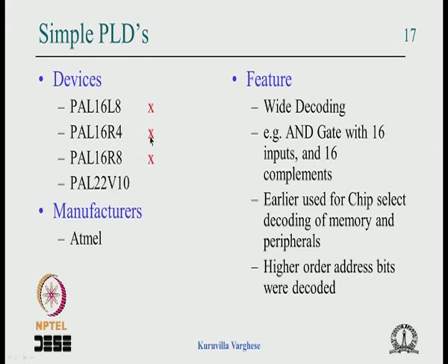It's of academic interest to understand, maybe the only device which is being used nowadays is among the complex PLDs. So the PAL22V10 is a much more flexible version, which combines all these together. We will see that architecture, and Atmel still manufactures this PAL22V10. It may be useful in very small processes like glue logic, when you want some kind of logic where it needs to be programmable, then you can use that.